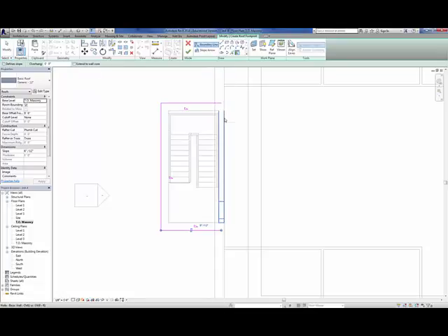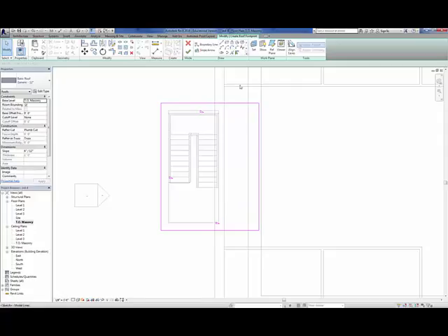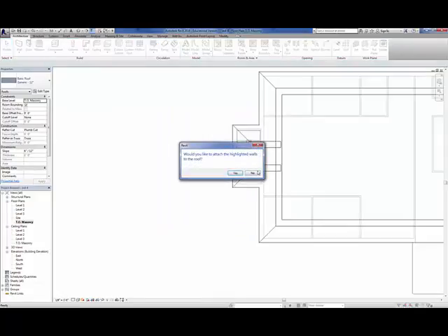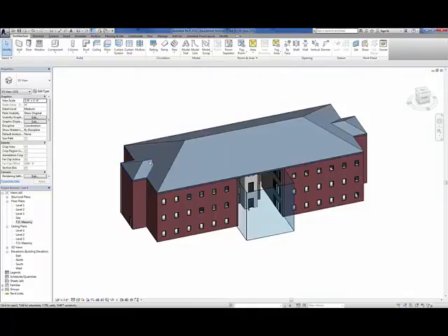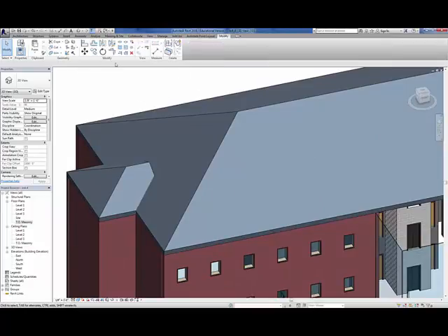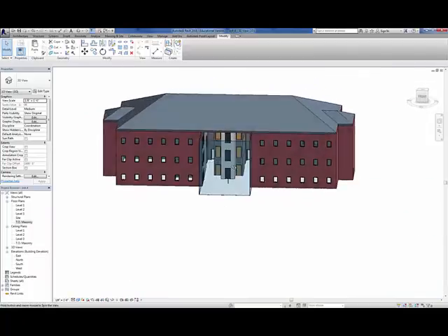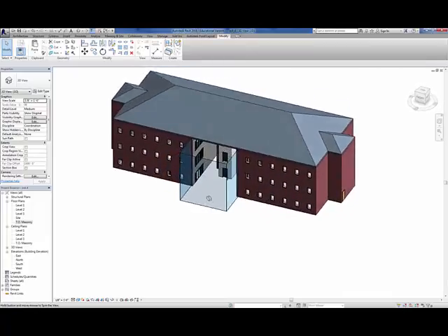I'm going to select this wall, and we're going to move it in another 6 feet again, because the only way to use the join unjoin is if the roofs actually intersect in some way. So we're just bringing them in 6 feet. If they went even more, it would work, but we need to be able to select this edge right here. So let's finish that. No, don't change the roof. We go into the 3D view because that's the easiest one to work with for doing it. So let's go to modify, join unjoin, edge of the stairwell roof, face of the main roof. And there we go. Now you can see we've got those two additional roofs that are set in, and in doing this, this creates the ridges and the valleys for all that work.